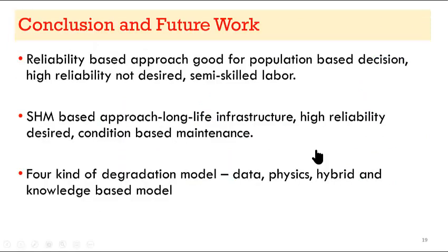So what are the conclusions of this presentation? We discussed two approaches: one is the reliability-based approach, another is the SHM-based approach. The reliability-based approach is good where you require a population-based decision and you don't require high reliability. In case of the SHM-based approach, if I have a system that is a long-life infrastructure, or high reliability is desired, or we require condition-based maintenance, in those cases we use the SHM-based approach.